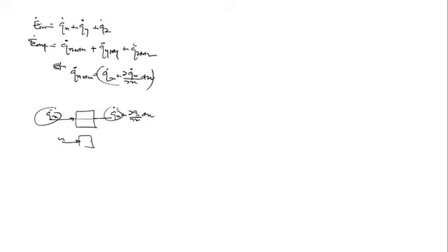Since q dot x plus dx, my dear, is nothing but, from the Taylor series, simply q dot x plus del q dot x upon del x into dx. I told you already, it means how much change there is. Just like in fluid mechanics, u here, then u plus del u upon del y into dy. Same thing: u at x, then u at y, then u at y plus dy. This is simply from the Taylor series expansion.